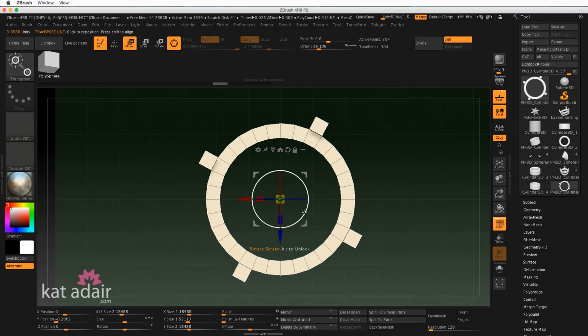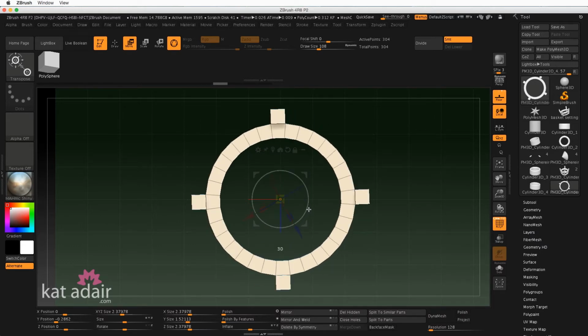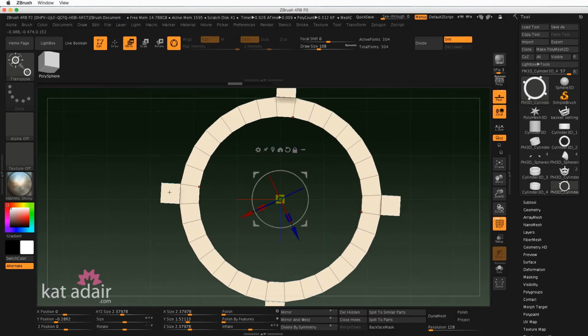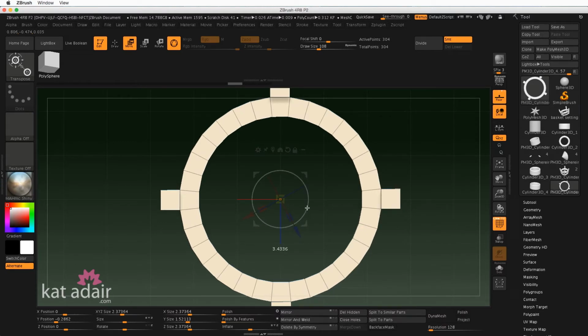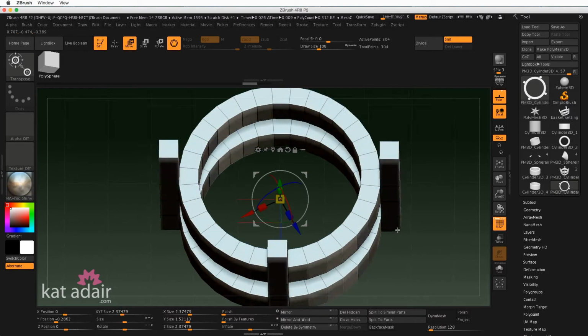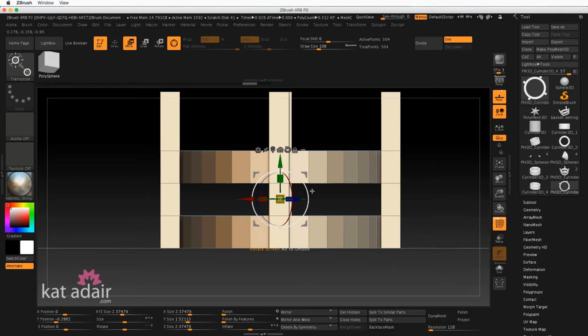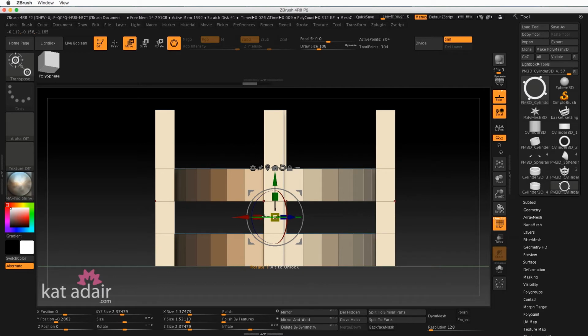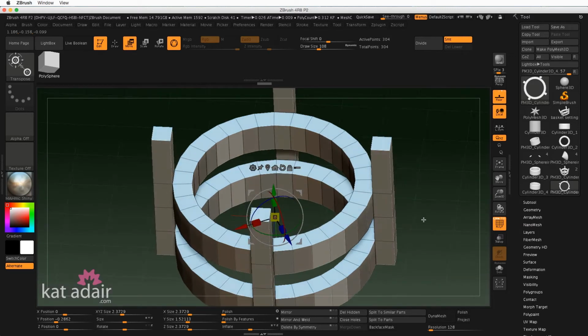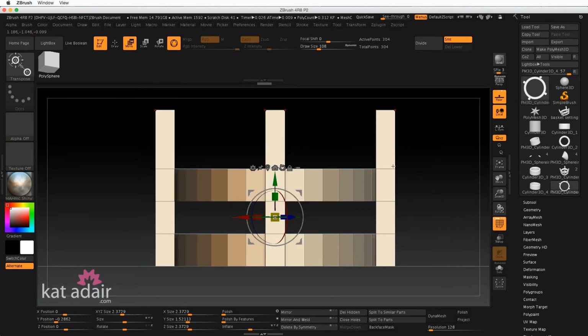I'm grabbing onto this white ring, clicking, and I'll hold the Shift key, but notice it's not lining up. I don't have the prongs exactly on either side. So I'll just have to eyeball that a little bit and make sure that it's somewhat lined up, and that looks pretty good. Oh, I could rotate it a little bit more. I'm on the side and I'm looking at this center prong. So what I'll do is grab this green line and then rotate a little bit more. And now those two prongs line up perfectly, which means that these are also lined up as well.